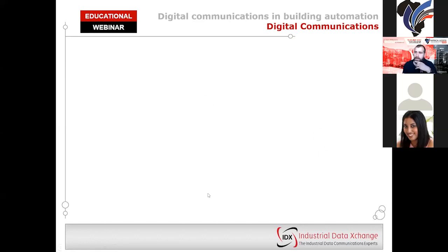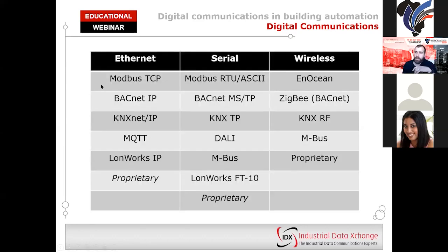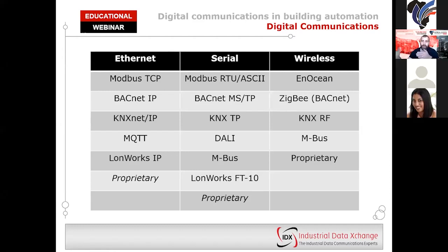So now, some of these protocols, for example, Modbus. Modbus is not only used in building automation, although it is very useful. It's also used very commonly in the industrial environment, home environments, and many more. MQTT, also used very often in the IT environment, can be used to link directly to servers on the other end of a WAN connection, meaning that it can operate as a language not only in your PAN space, but also in your local area network and in your wider area network directly.